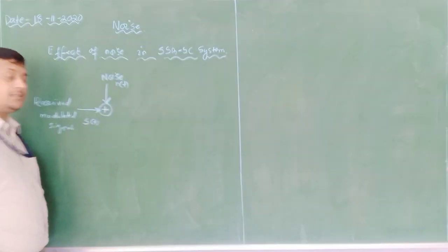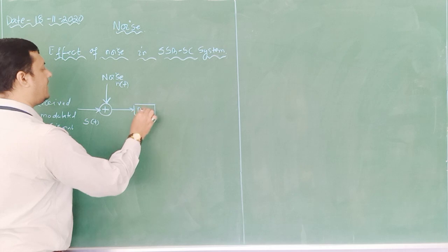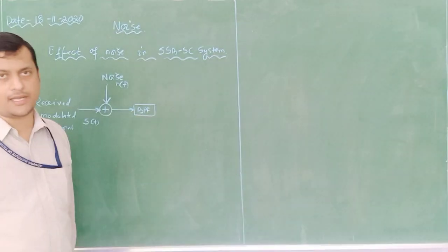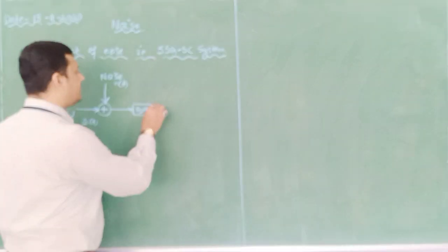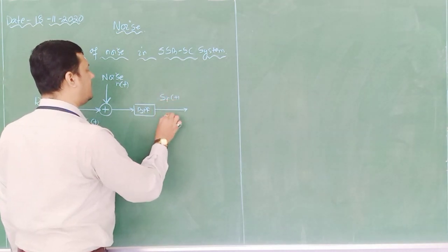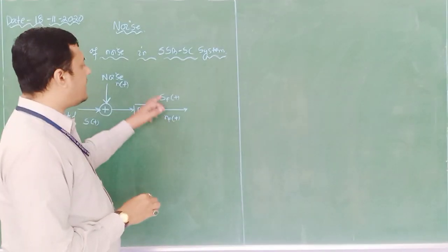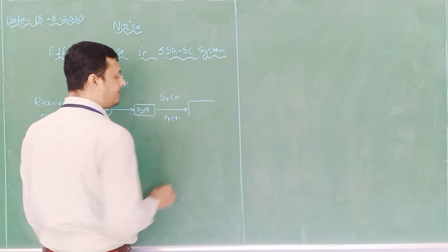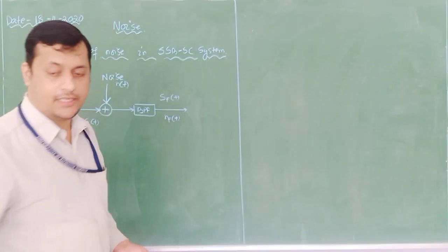Now at the receiver end, it must pass through the band pass filter because we need a certain band. With the help of that band, we will extract our information, either the lower segment or the upper side. Then the output of this band pass filter is s_F(t) and n_F(t). That we also discussed last class. We just need to identify this relation according to the SSB-SC system. And then it enters the demodulator.